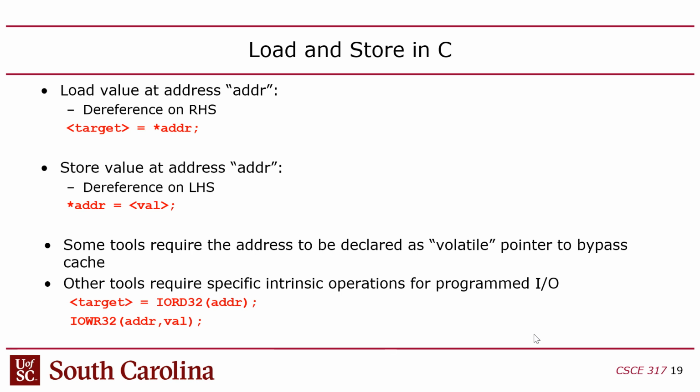So what do you do? Well, in that case, you have to make sure that you use intrinsics. Okay, so in the case of the FPGA, there's an intrinsic called IORD32, which looks like a function, but it's actually a macro. And that intrinsic will get translated into a load I/O instruction. So same thing as a load, same thing as just doing an indirection, a dereference here, but it gets translated to the proper machine instruction so it bypasses the cache.